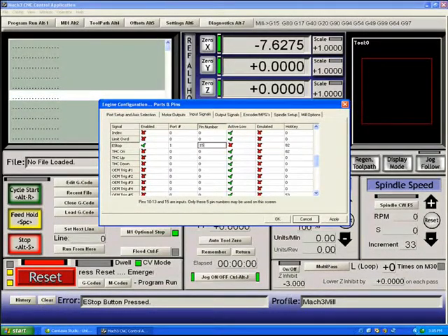Pin 15 would be fairly typical, and will do the job for you. You can see that the active low is checked off. Therefore, a high signal is what is going to trigger an e-stop. At this point, you can pretty much stop using this configuration.